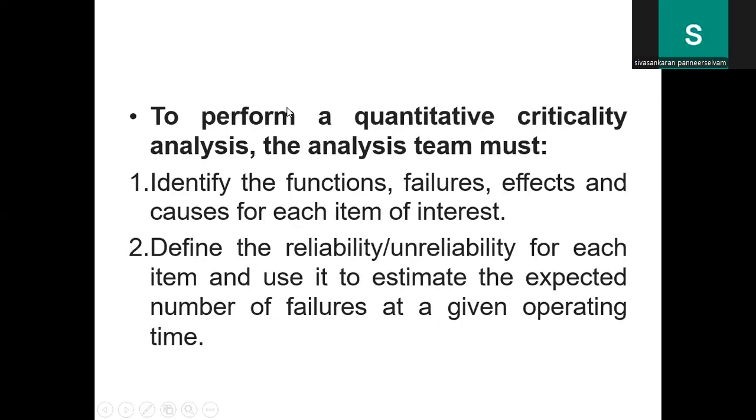So how do we perform the failure mode effect analysis? Apply a quantitative method by constructing a form or template sheet called a failure mode effect critical analysis chart. In the chart, first write down the product functions and list out the potential failures experienced by the product when it is in operating mode, and the various root causes and side effects of each item.